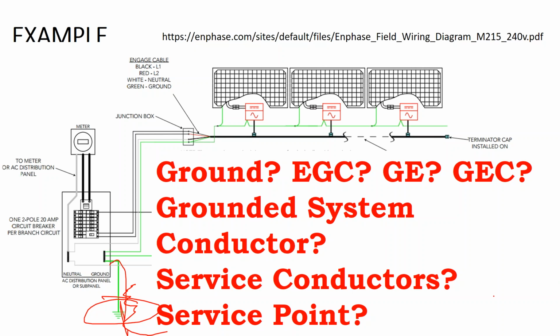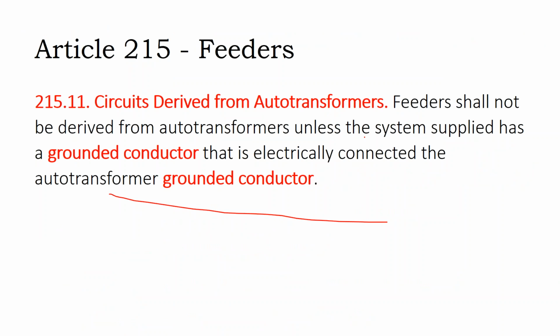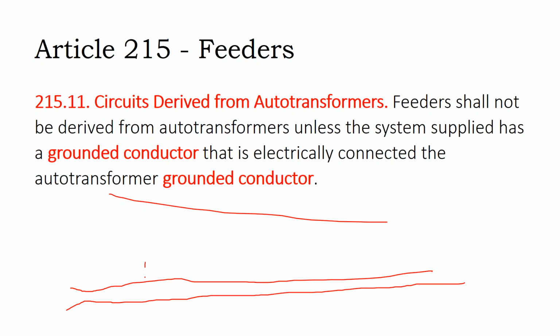In Mississippi, it used to be the bottom of an ocean floor, so very high pressure, just about 2 or 3 feet of sediment, and as soon as you get through that sediment, you get hard concrete rock shelf. So you take a ground rod, an 8-foot ground rod, and it only goes in about 3 feet. Then per code, you're allowed to tilt that ground rod at 45 degrees, and then it only goes in 4 feet. And there's not enough resistance in that to ground.